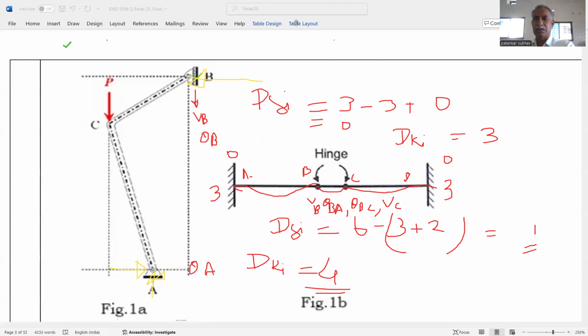So I think using this simple concept, degree of static redundancy is equal to external redundancy plus internal redundancy. External redundancy is related with the reaction component, that is the external support, and the equations available, and internal depends on the type of structure. In case of beam, it is 0. In case of frame, we have considered 3 times A, where A is the closed areas. And in case of truss, we have considered M minus 2J minus 3 in bracket.